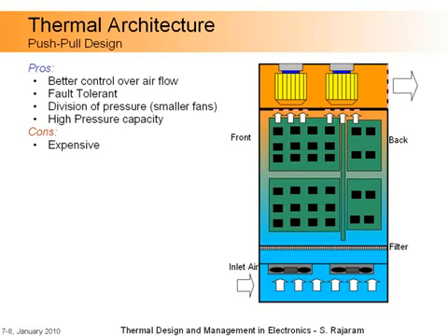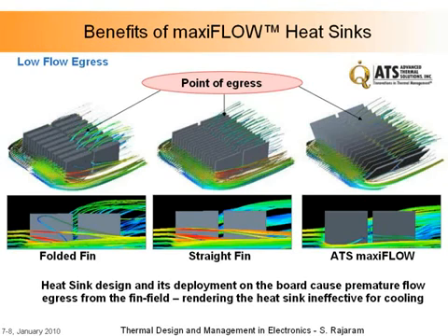Now, when we go into selecting heat sinks, you remember what happens when flow goes over bodies. What happens when there's an obstruction? Flow will tend to bypass the obstruction and separate. So if you have a heat sink on top of a device, if the flow does not go through the heat sink, you're not going to cool it. So look at these 3 designs. Notice that in this one, the flow is separated. It is not going over the heat sink.